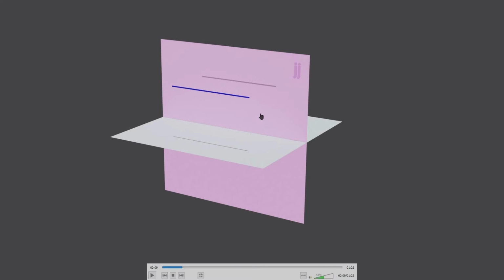Okay, now as we have done for points and the basic introduction to orthographic projections, we have marked the front view and the top view. So we are going to do the same thing here. I'll just mark the front view, top view, everything. Okay, so I've marked A prime, B prime as the front view, A, B as the top view. Okay, the naming is like that. A prime, B prime is the front view, A, B is the top view.